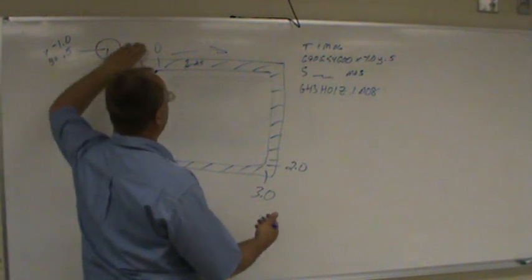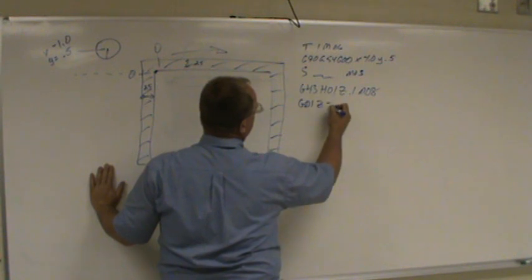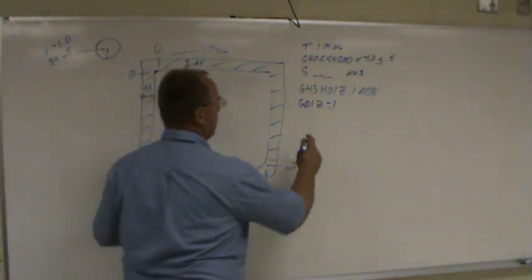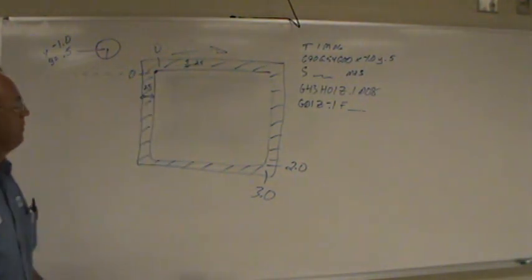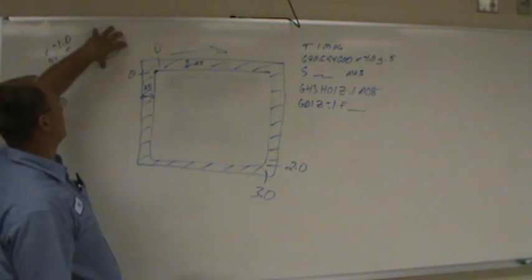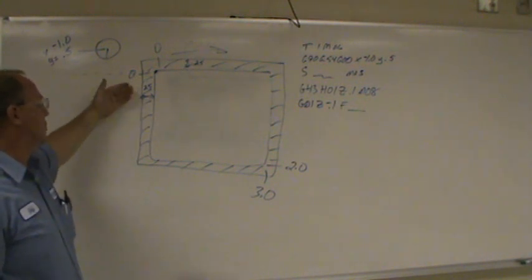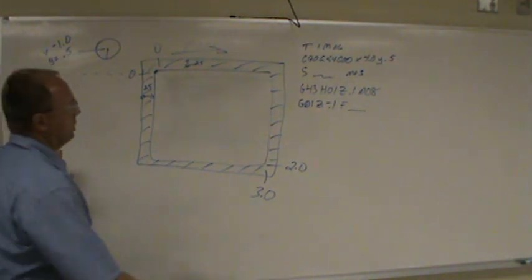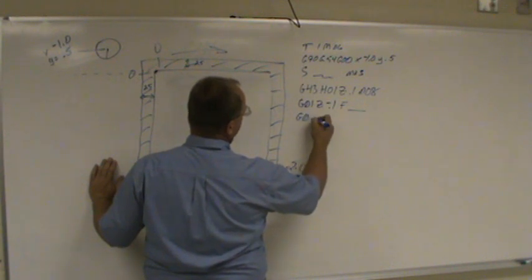Next step would be to go down into your Z depth. If you want to go G01, Z -0.1, and because this is the first time we're using a G01, you need a feed rate, whatever that may be. So at this point in the program, our tool's over here, turning at whatever RPMs we told it to turn, -0.1, so it's below the top of the part and it's ready to start cutting. We're already in G01, you don't need it, you can put it in, doesn't matter.